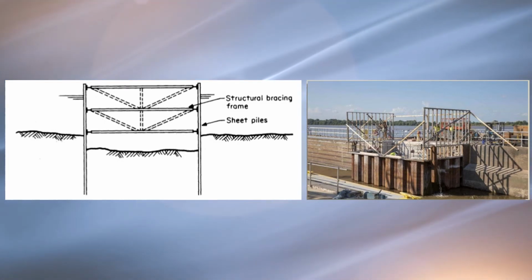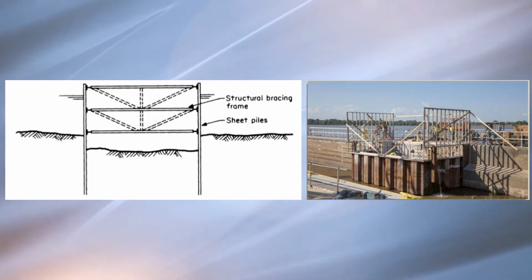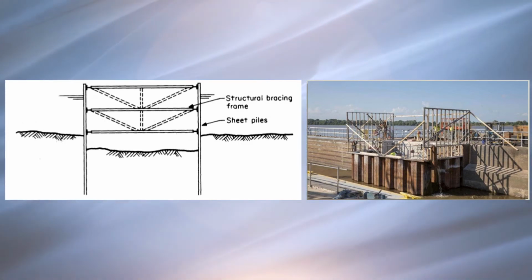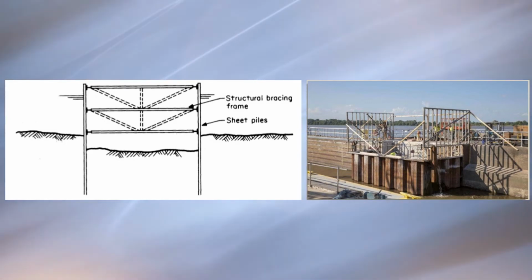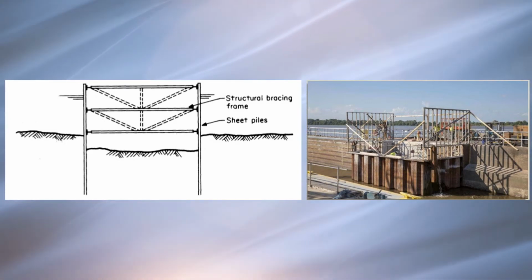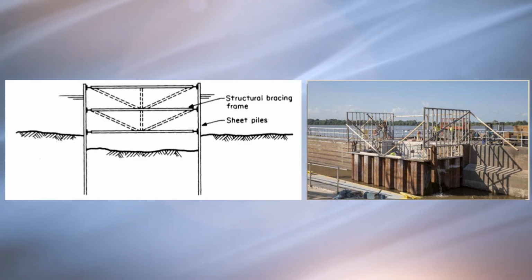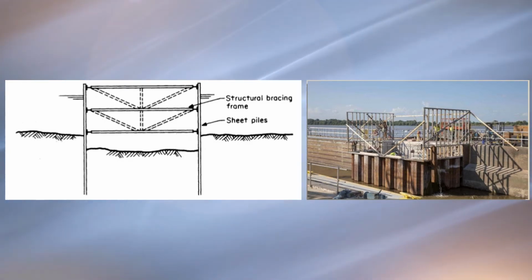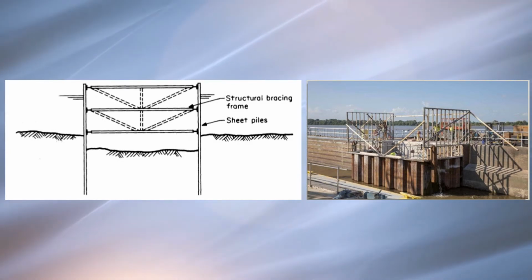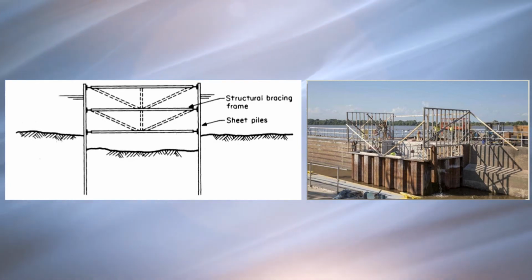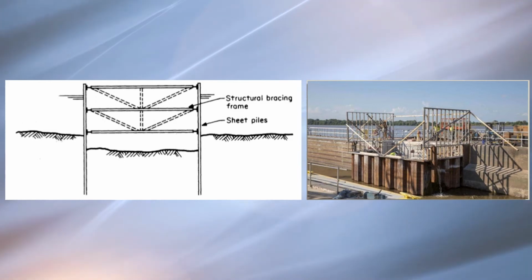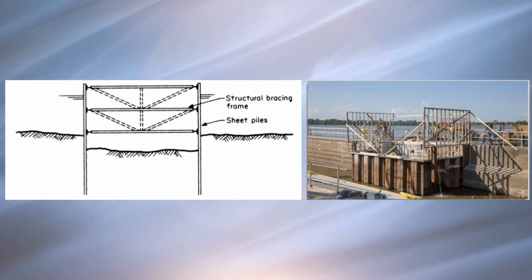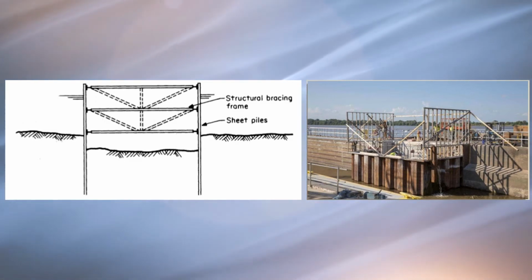Placement of an underwater concrete seal course is the fastest and most common method. Where the cofferdam structure can be built on a layer of impervious soil, which prevents the passage of water, the area within the cofferdam can be completely sealed off. Impervious soil is soil which offers maximum resistance to the flow of water, such as silts and clay.